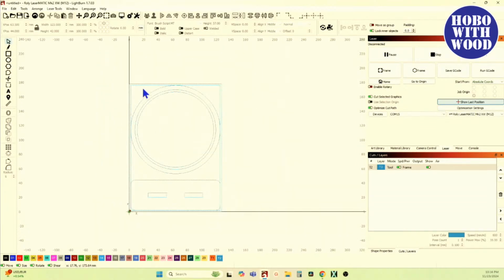Now I've still got this main rectangle out here that's 2 millimeters from the edge of the entire design. So I also now know that this is 42 millimeters. And what I didn't do a minute ago when I did the math to figure out the new overall height is I forgot to subtract the additional 3 millimeters. So that base I just did the math on is 6 millimeters wide plus 18 on either side. It's 36 plus 6 is 42 mil.